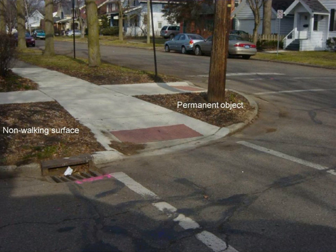Now, if you don't have a walkable surface on either side, or you have a permanent object, then you can use something that's more of a rolled curb. It doesn't necessarily have to be vertical. There's really no requirement for how much slope that side flare has to have. It just doesn't have to be limited to that 10% maximum. I know that I've seen some slides with a perpendicular curb, and I know here in Michigan the snowplows absolutely don't like that.